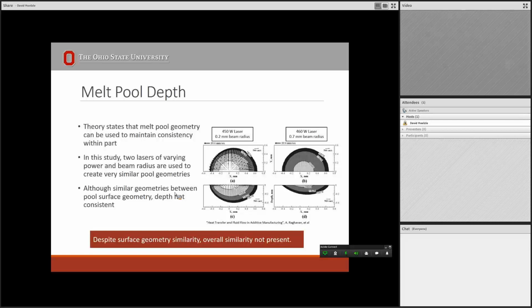So you see a very, it's tough to see, it almost looks like little dots on the right, because this is the velocity of the flow above, which is varying by the convection. On the left, it's taking material at the very center of the laser, which is the hottest, and via convection moving that to the edge, and also having it swirling down. That's the major effect of flow above. It's deepening the heat transfer from the center to the edges, and also it's rotating down. So it's a very effective thermal pathway to make the temperature of the bottom higher.